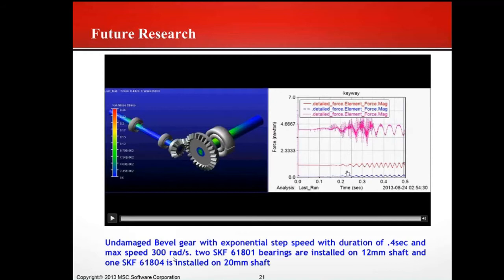But when the speed gradually increases, it causes vibration oscillation, which makes sense because we made the shaft a flexible shaft. So View Flex is a really powerful tool in Adams, because you don't have to resort to FEA. There's an embedded solver to realistically simulate the whole system.